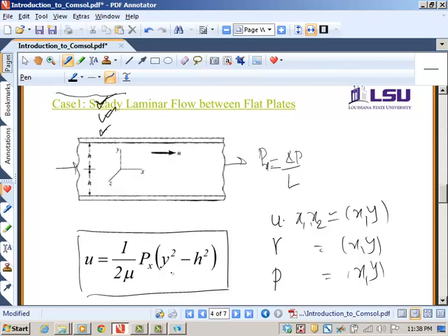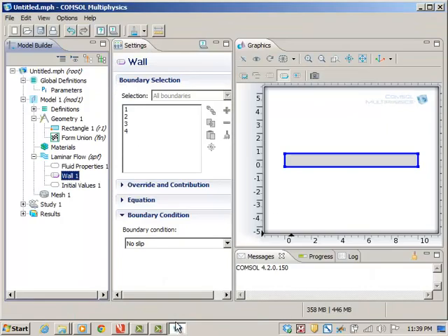So we're going to use a periodic boundary condition to model this case. So in a periodic boundary condition, we choose a source cross section and a destination cross section, and the velocity profile at the destination is the same as the velocity profile at the source. So it means whatever flow is here, the same flow is applied at the inlet also. So it is like a fully developed flow assumption, and we are neglecting the entry and exit effects in this case. So let us apply this boundary condition, and this is inbuilt.